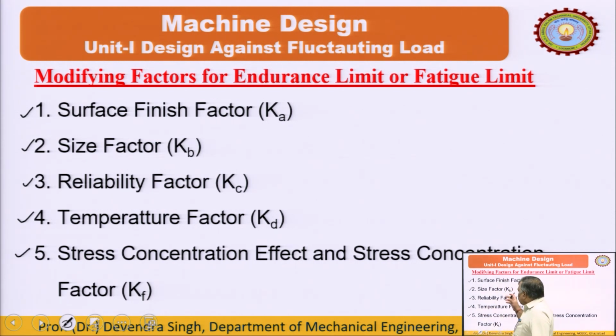Then we use this size factor. Every material has some defects, so those defects in the crystal structure may act like a crack. If the size is more, then the probability of any dislocation, any imperfection to initiate or work like a crack is higher, and then further it will propagate. Those chances of failure may be increased. So, to incorporate this effect and to avoid the failure due to this dimension, we use the size factor to modify the endurance limit.